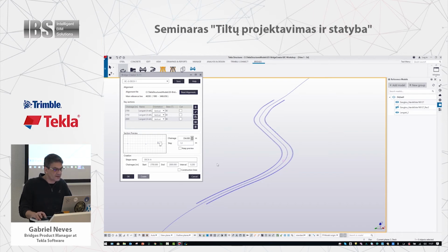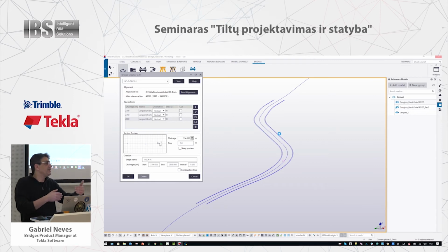It's 100 meters long, and it's 3 key sections. Because after I do this one, I'll show you the precast scope. To do the precast scope, what I did was give me 10 meters, from this change to that change. And then 25 mil spacing. Next scope will be the previous change plus 25 mil and then 10 meters extra.